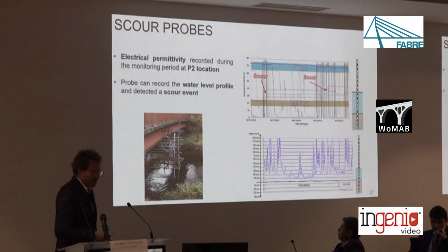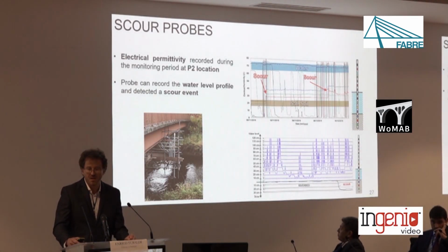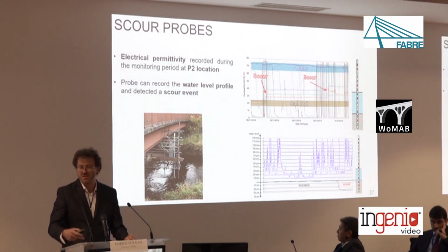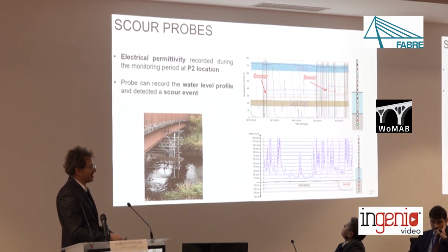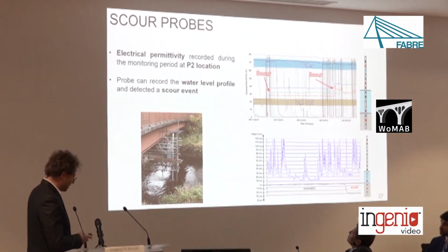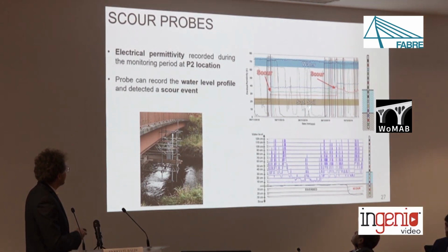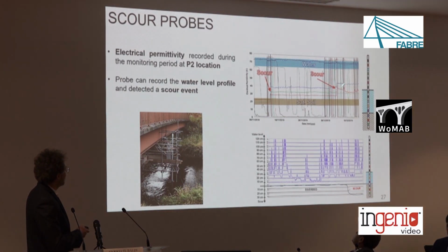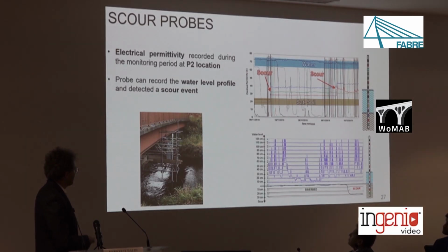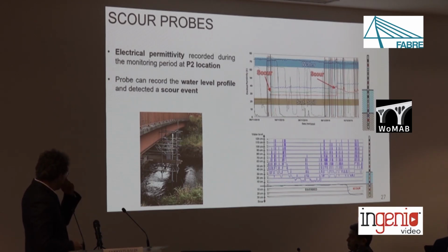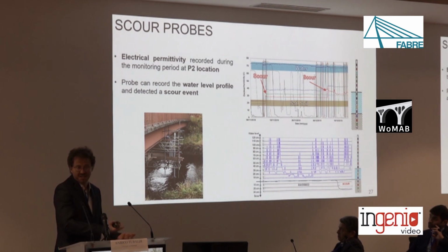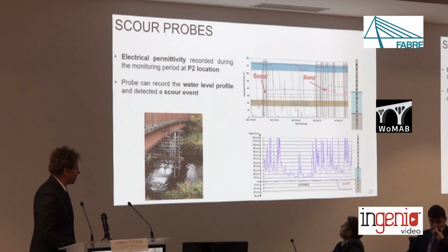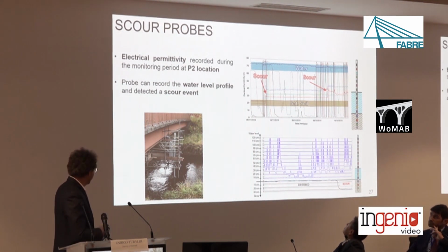These sensors have provided continuous measurement of the water level and of scour over the years, with some interruptions due to COVID and the problem in replacing the batteries. Nevertheless, they detected only a minor level of scour of 20 centimeters under a relatively mild flow level, and we were able to validate this measurement by going to site and using a probe, so to manually evaluate the change in riverbed depth.